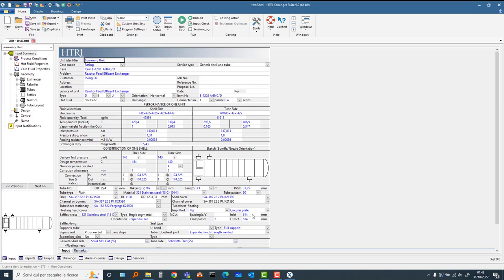Moreover, we have to see that the distance between the inside part of the tube sheet and the first baffle, and the distance from the last baffle to the tube support, this is a full baffle before the bends, in order to support all the tubes before the bends.